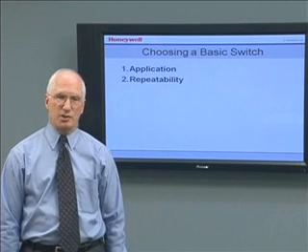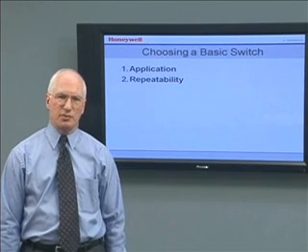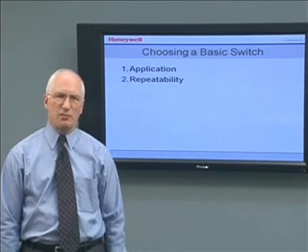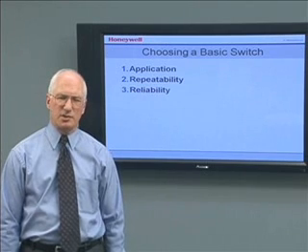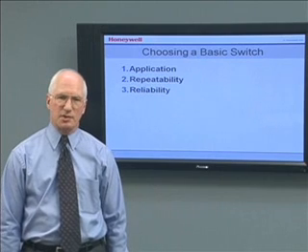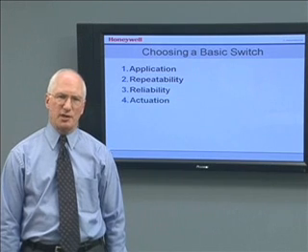Repeatability. The switch should actuate and release within a specified tolerance band every time. Of course, a switch with repeatability of 1 million cycles will cost more than one with only 50,000 cycles. Reliability. How many cycles of reliable switch operation does your application need? For example, a superior switch can operate for 10 million cycles before mechanical failure and 100,000 cycles under maximum load before electrical failure.